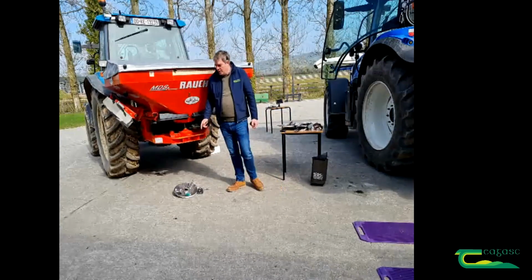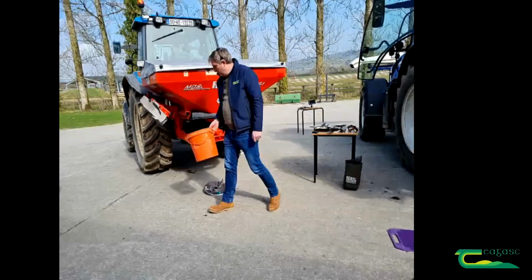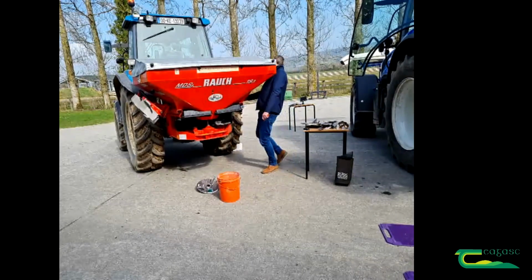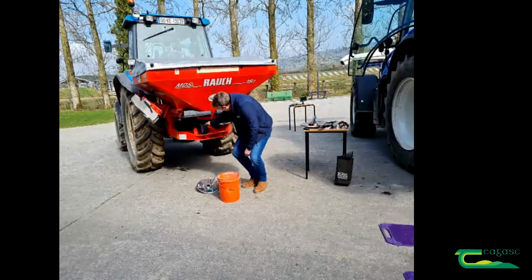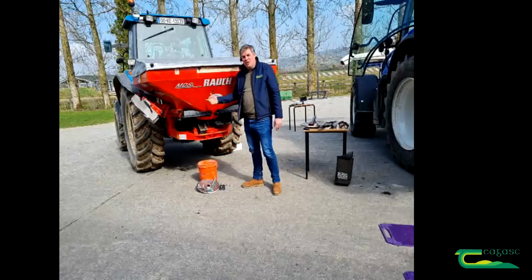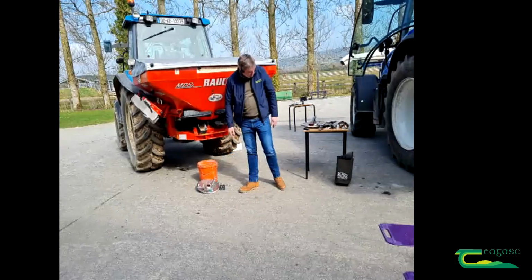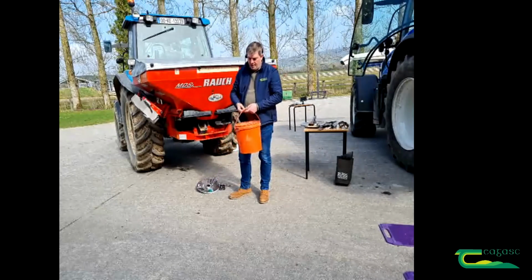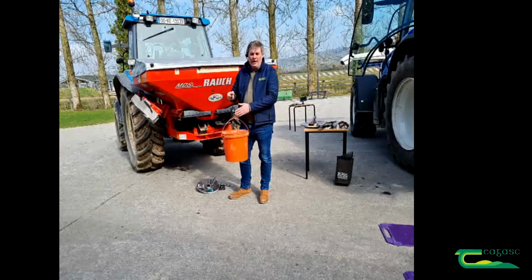The other thing that we do need to do is to measure the flow rate, okay? So the only way to do this on our basic machines is to take a bucket, okay? There is a unit here on the front of the machine. This little plastic funnel sits in here, okay? We put our bucket here underneath the machine, and then we'll run the machine for 30 seconds. We'll collect what fertilizer comes out in the bucket, then we'll get a scales and measure the quantity that's in that bucket, okay, and we'll see how that compares to what we should have.